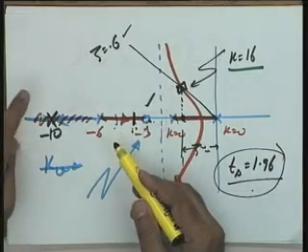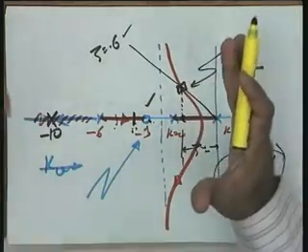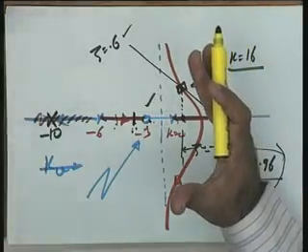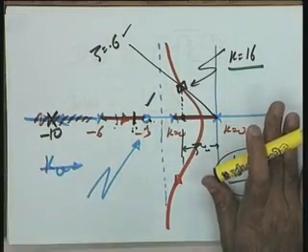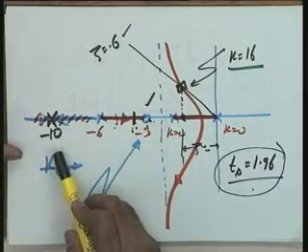If I place it at minus infinity, what will happen? When you realize it using an op-amp circuit, or even when you realize it using a digital computer, numerical accuracy requires some good numerical coefficients coming into the system. So at this juncture, I leave it to the realization problem. Practically, this should be as far away as possible so that the effect on this particular root locus is minimized. The filtering requirements and the realization requirements should dictate the third pole which should be added.